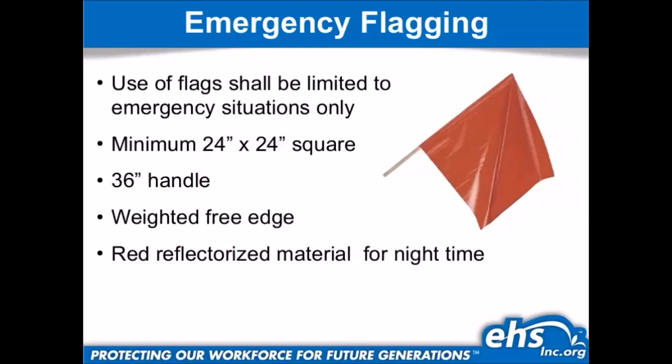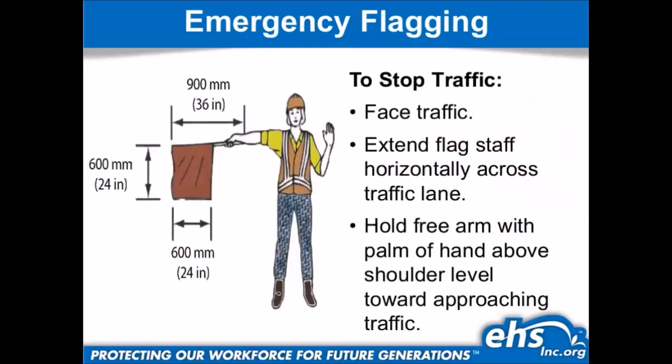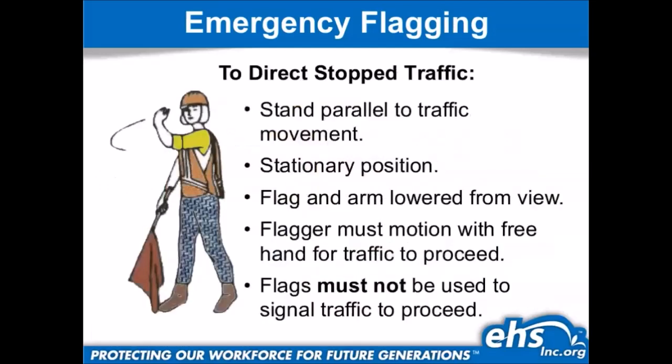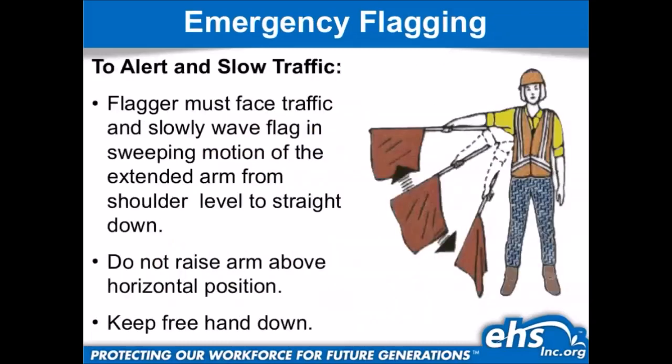So here are the requirements for these flags. The hand signals are pretty consistent. Stop is still stop: flag in the roadway like that, hand signal with palm facing the public. Proceed, you drop the flag hand down and you wave them by, just like you would with the stop/slow paddle. The one that changes is to alert and slow traffic.